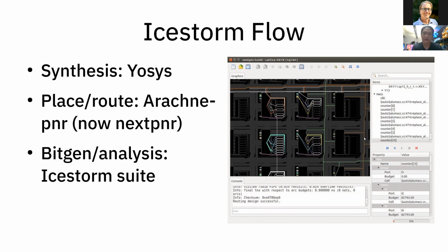So one of the interesting things is that I think they've tried really hard to extract the timing from these devices, but I still suspect that I'm getting some odd corner cases that don't work, because a lot of it had to be pulled out from vendor files and reverse engineered, and it's a really subtle thing to try and figure out. Particularly, when you go through multiple nets, you have to go through multiple switch points, and each of those is like a pass gate, and each of those has a resistance that can corner to a different set of corners.